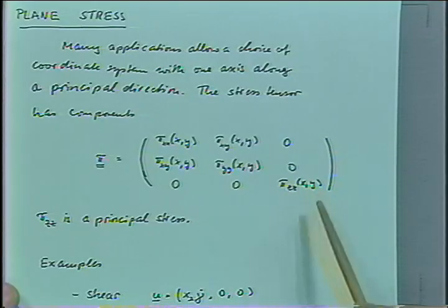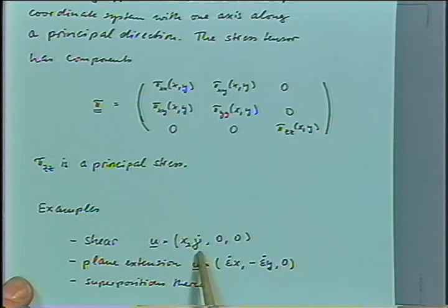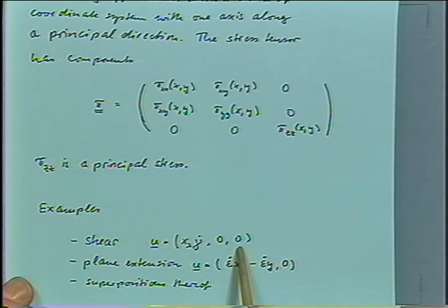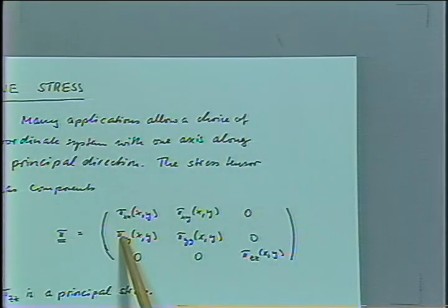One common application for the plane stress is shear flow, where we have action in the one direction and two direction. One is the flow direction, and two is the gradient direction. Three is the neutral direction, and that's always a principal direction for the stress. And we would simplify our stress tensor in that format for describing shear flow.